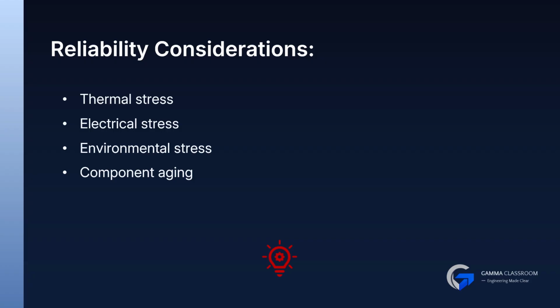Proper derating, ventilation, and maintenance planning extend inverter life. Reliability is not just a hardware issue, it's a design philosophy.